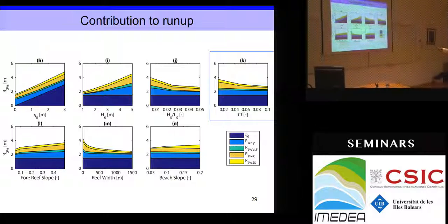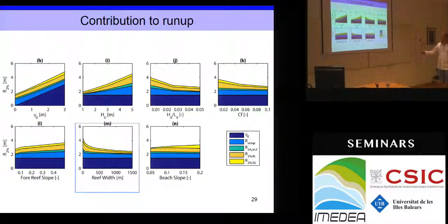Friction coefficient, small friction coefficients, higher water level. This is not that important. This is an interesting one, where you see that if the reef width is decreasing, if it gets smaller, you can get suddenly much higher run-up levels.